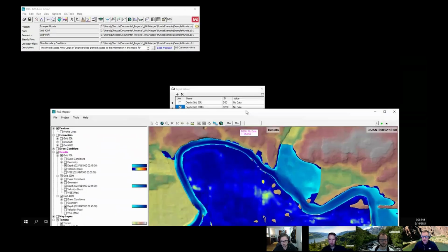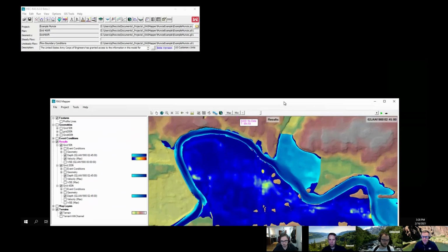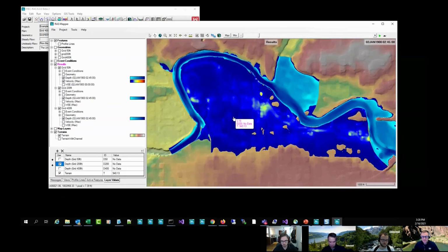This is a great tool if you want to compare inundation extents between 2 different plans. You could turn on your water surface elevation for both and animate them, and they'll animate together by doing this watch list. Correct. That's awesome. I think this has been super helpful from an engineering standpoint when you're doing that levee design and you want to know, how high is my water surface compared to my levee for my 3 different plans. You can turn them on, have that terrain with the levee layer turned on and just compare the different ones. So super helpful, I think.